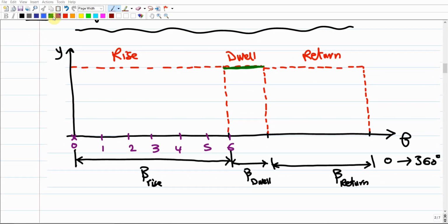So from the middle of this y-axis, from the midpoint, you're just gonna mark a point. This is gonna be the center point, and you're gonna use the compass and fix the metal needle of the compass here, and touch the lead point of the compass at this point, and just draw a semicircle, a half circle, in this way.